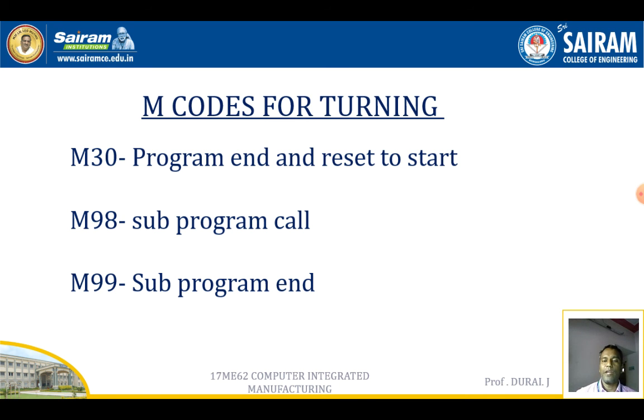And M98, subprogram call. Suppose some profile has a mirror image or a copy available, at those times you can use this subprogram call. That means we make the program for only one particular profile, and we can make its mirror with the use of this subprogram call.